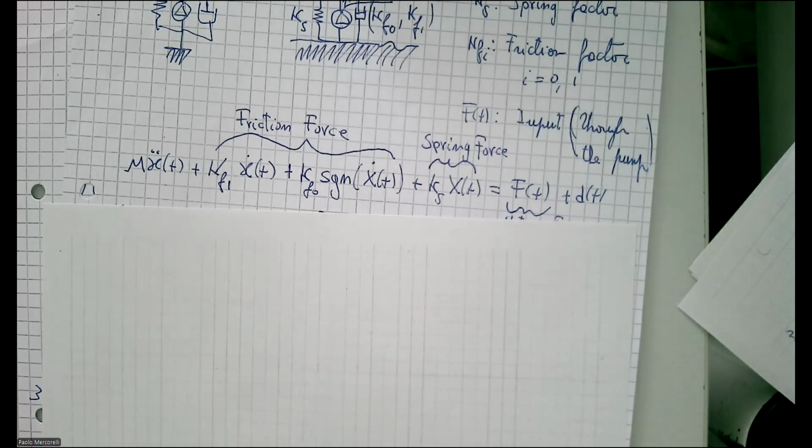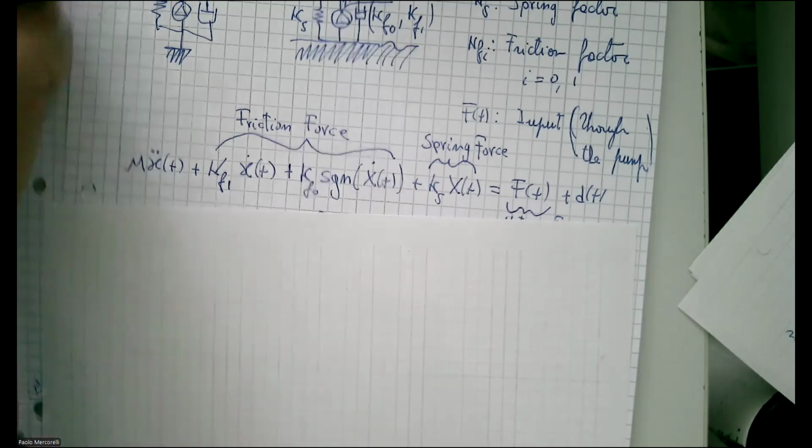Do you remember this SGN? SGN is impossible to realize exactly as a mathematical function, because this means it changes in an infinitely small region. I will change between -1 and 1, not only. Practically, I will change between minus beta and beta. Beta could be also very large. Remember, it must compensate what I don't know. This means practically it's impossible. Therefore, we approximate with other sigmoid functions. Remember, hyperbolic tangent, arctangent, or different, also other functions.